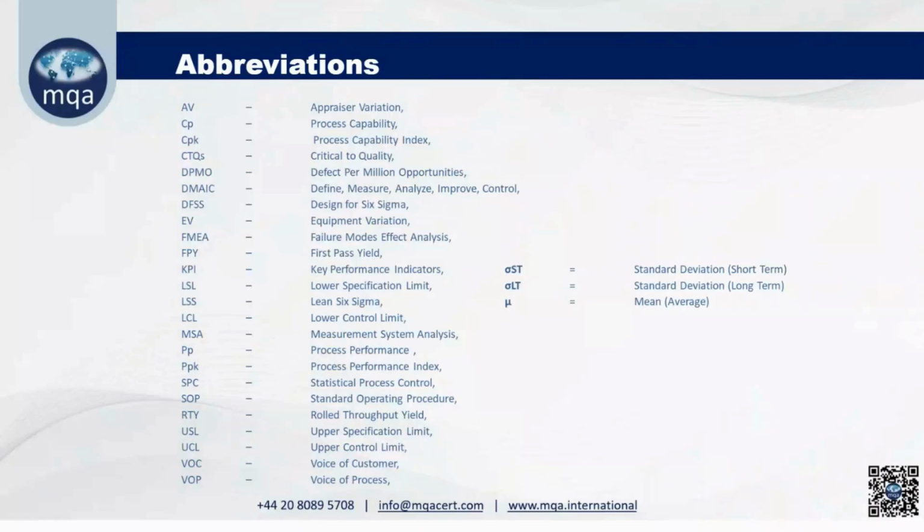Thank you, sir. We have X double bar, which is the average of X bar. Okay. So we have the upper specification. We have CP and CPK: process capability and process capability index. What is CP? CP is tolerance upon 6 sigma. Tolerance means specification.